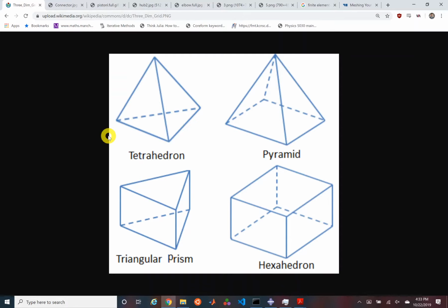For instance, in structural mechanics, linear tet meshes will give you the wrong results. Some people will say that they're over stiff, but I prefer just to say that they're wrong, that they're not sufficient for structural mechanics analyses. And so you have to use degree 2 or quadratic tetrahedral elements in structural mechanics problems. What you tend to get is that the problem blows up, where you just get a lot of degrees of freedom.